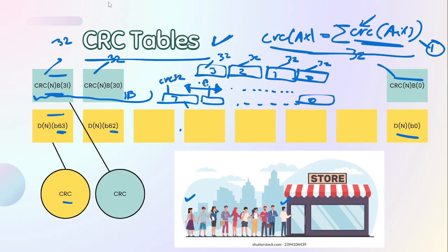Because you have to see, if that was the only thing you were dealing with, the table just evolves these. The table will evolve just by looking at 1 byte. It doesn't even know these exist. Likewise, when you look at this one, it doesn't even know these exist. So the tables think of each component. It's like a Fourier transform. Each of these components is seen in isolation, and then at the end of it, you just sum all of them. You take an integral over all of those components. A sum over all those components gives you the final CRC of that clock cycle.